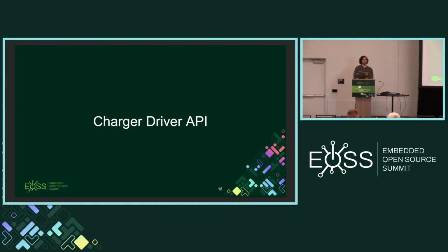Right. So there are resistor-strapped charging ICs where you just place down various impedance values on a pin and you set some of those thresholds. But being able to talk to the charging IC itself has the advantage of being able to respond to certain events in software. So it's not just a fixed static charge profile.